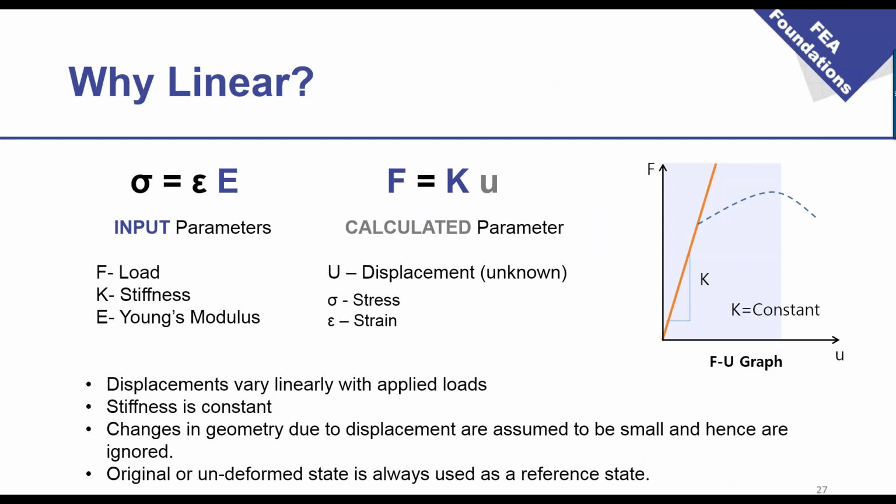If we go to the material conditions, once again, Stepien was explaining why linear static. Just to remind you quickly, there are two equivalent formulas. To the left, we have the equation which describes Hooke's law using the stress, strain, and Young modulus. As you see, the Young modulus stands for the input parameter, which I was defining. In the equation to the right, F stands for the load, and I was applying my moment.